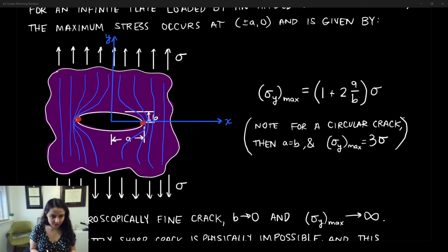So we're not talking about a change in cross-section. We are talking about a change in geometry. We're talking about a concentration of stress at an edge, at a defect. And really what we're talking about is the change in surface energy that it takes to propagate a crack. So the energy that it takes to actually form two new surfaces. But again, not going to get too deep into the energy release rate discussion here. I just wanted to make that point that this is different from what we've seen before.